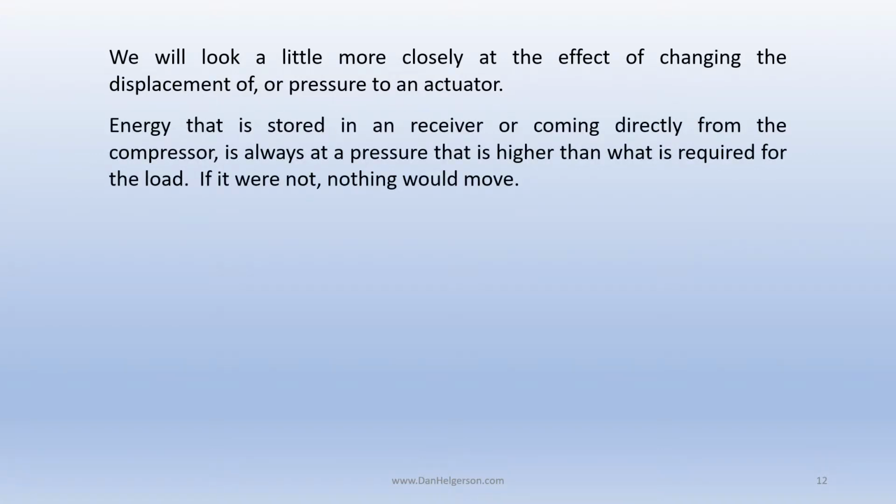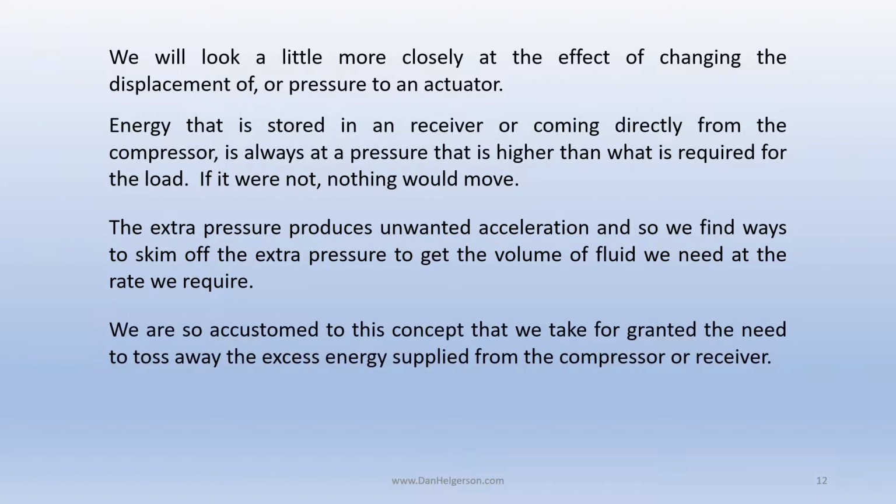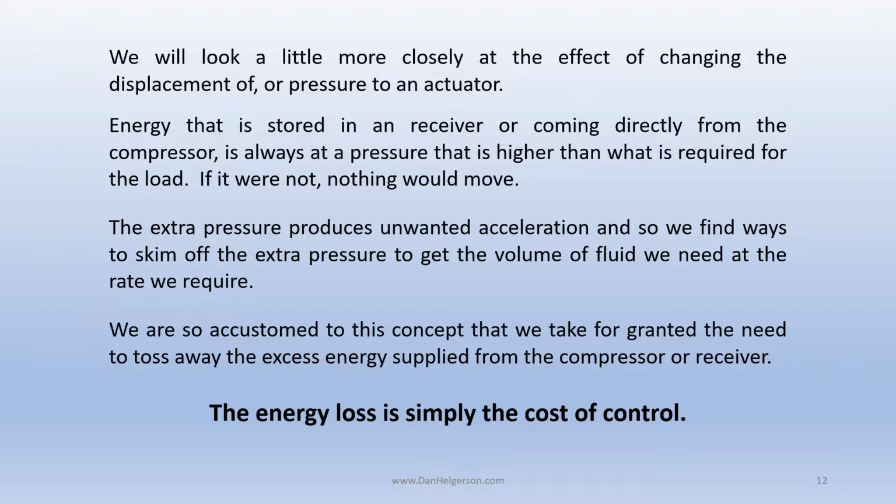We will look a little more closely at the effect of changing the displacement of or pressure to an actuator. Energy that is stored in a receiver or coming directly from the compressor is always at a pressure that is higher than what is required for the load. If it were not, nothing would move. The extra pressure produces unwanted acceleration, and so we find ways to skim off the extra pressure to get the volume of fluid we need at the rate we require. We are so accustomed to this concept that we take for granted the need to toss away the excess energy supplied from the compressor or receiver. The energy loss is simply the cost of control.